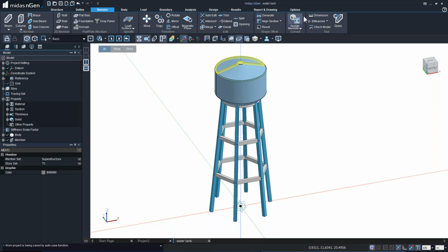Then further, we have the option to do the measurement, and you can even change the height of your members using the dimension command. So you can click on dimension. It's just an example that I'd provide. And with this, you can simply, let's say 5 meters and click on OK. So in this way, you can reduce the height of any of the members as well, like reduce the length or depth of any of your member.